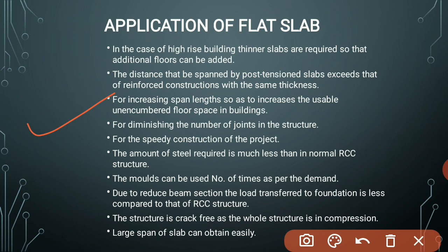So if we have to go for a high rise building where we have the ability to provide a smaller thickness slab and get the maximum area or maximum space out of it, then in that case we'll go for a flat slab.